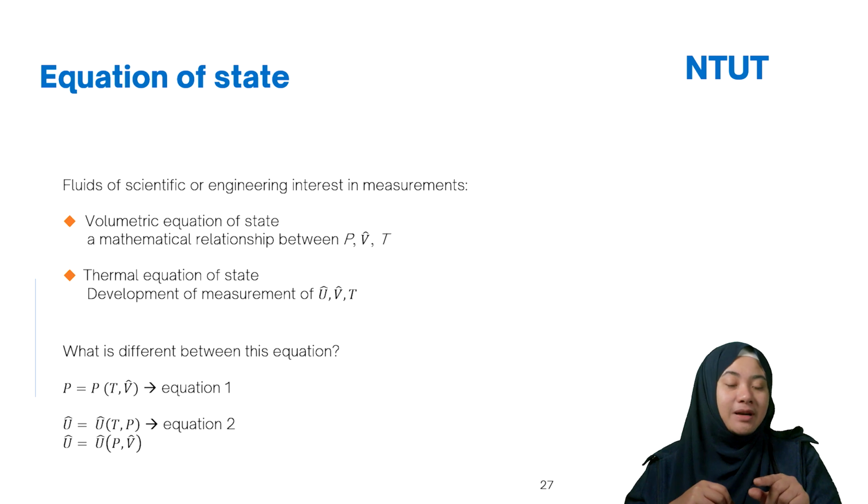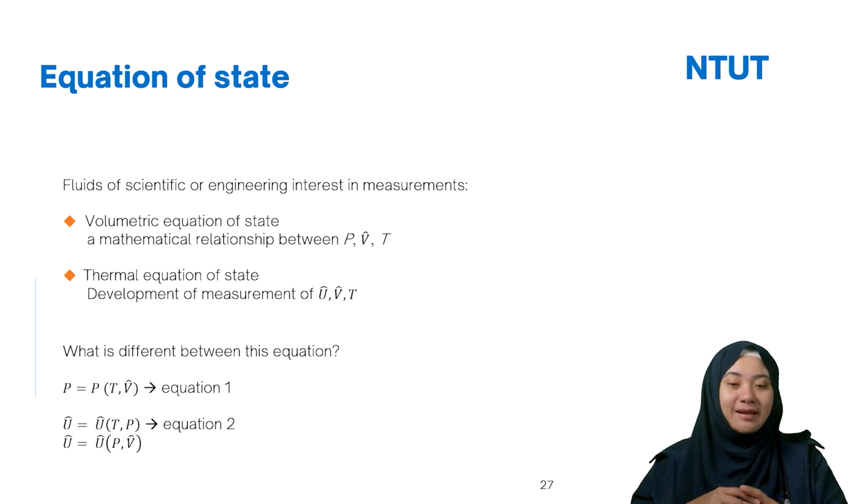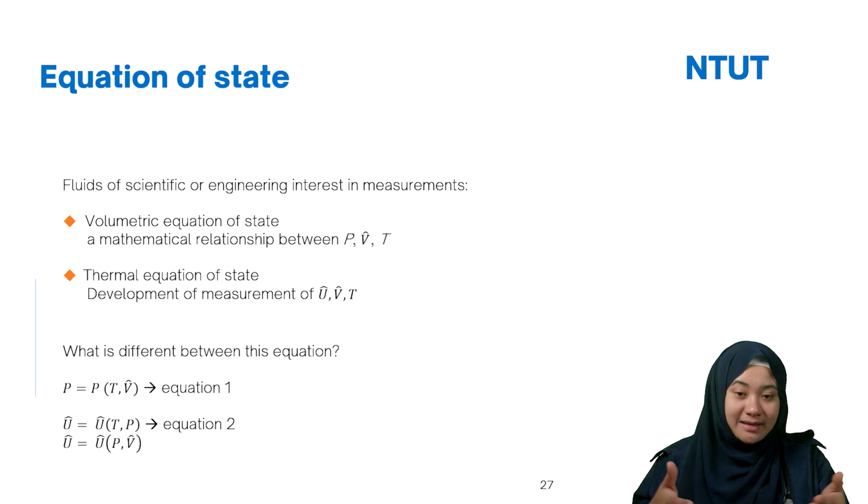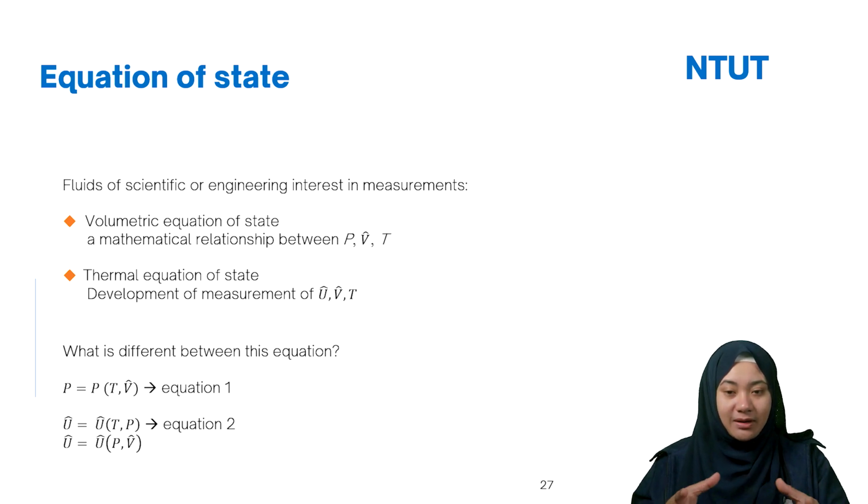So why do the pressure and the temperature not have a cap or an underline? Because they are not unit-based. It doesn't matter about the size, right? We call it intensive property. So the pressure and the temperature are intensive properties. They are not extensive. It doesn't matter with the mass. Mass and molar mean the unit depends on the size, so that's why they don't use the cap. The pressure and the temperature, we can use equipment to measure.